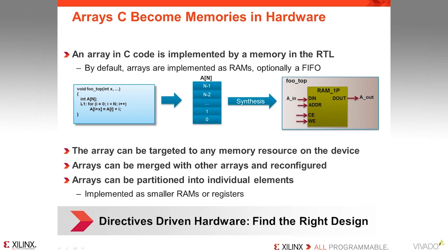They could be synthesized into block RAMs or LUT RAMs, single port RAMs, dual port RAMs. Any resource on the memory device, an array can be targeted to. In addition to that, arrays can actually be merged with other arrays. So if the user has a design with lots of small arrays, you have many arrays using up only 10 elements. Each one of them would use up its own BRAM. You could actually merge all these into a single BRAM. So the user doesn't have to change the C code. You could actually just merge all these together.